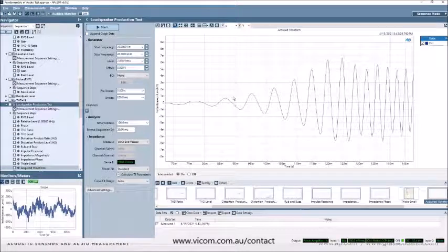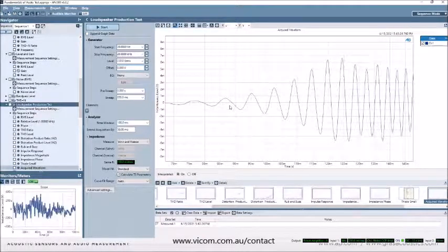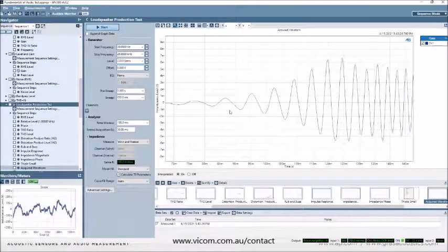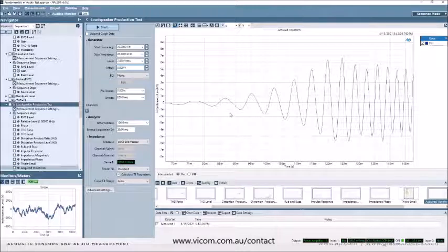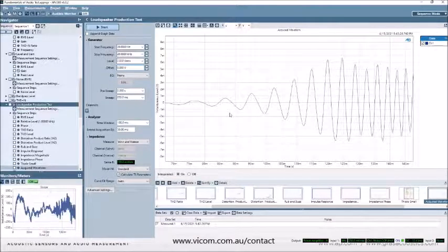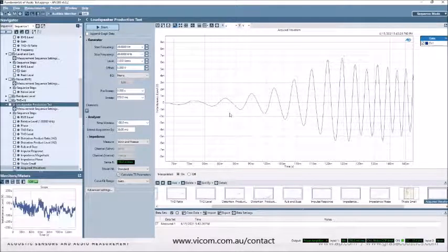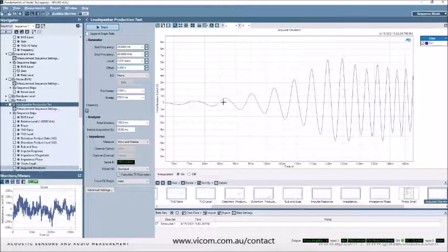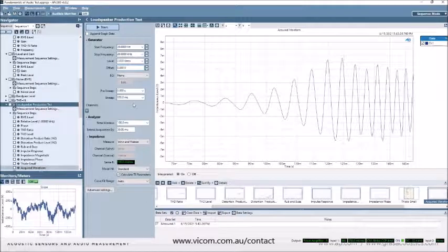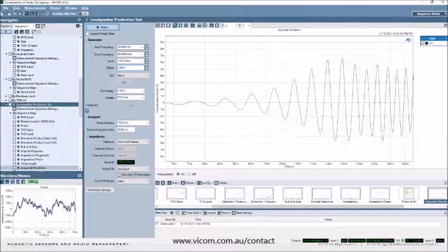So in the different types of sweeps, such as a classic step frequency sweep, the signal generator would actually dwell at each step, each fixed frequency, for a period of time. It would be no different than if we generated a standing signal and manually incremented the frequency.